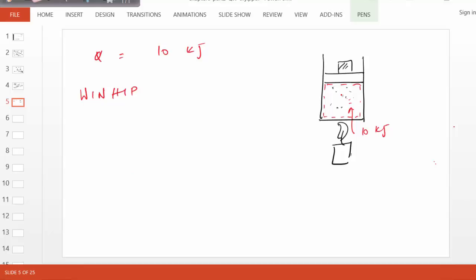My next question could be, what do you think happened to energy? Does it increase, decrease, or remain the same of the gas? Recall, energy is KE plus PE plus EU. Well, you might think that the PE must be going up because the center of gravity of the gas is going up. You may say, kinetic energy, does it change? No, right? It doesn't change, because for the kinetic energy to change, the entire piston cylinder device has to move. So PE change, as you start solving problems, you'll find gas has such little density that change in PE is almost negligible. Even if it changes, it increases so slightly.